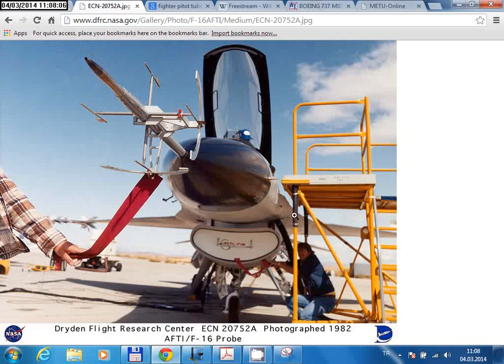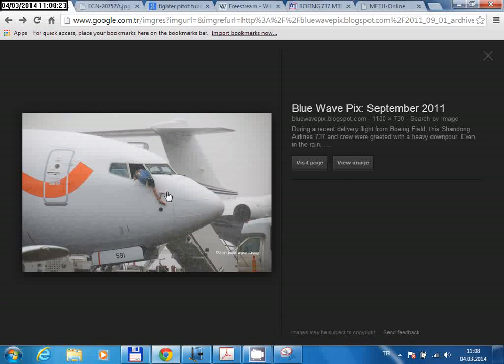In other words, if you see a measurement here, you compare it with the other data, and you say that if I measure this value here, the actual flow speed must be this. And that's how you obtain these calibration tables, and then you use them. So even though you know that you don't have free stream conditions here, using these calibration tables, you can get a better estimation of the real free stream velocity.